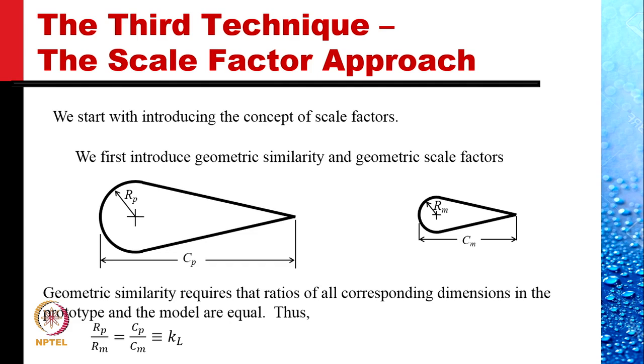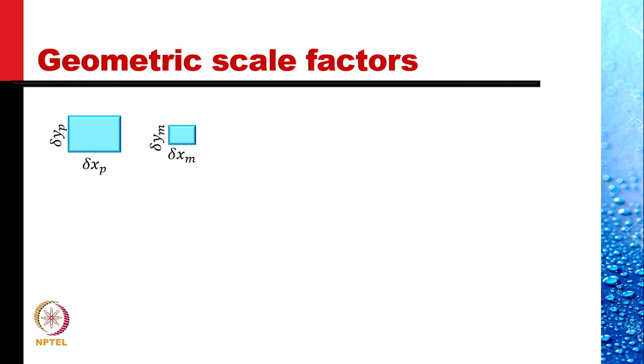So, scale factor is equal to the value of a parameter in the prototype divided by the value in the corresponding model. Let us consider two areas, one in the prototype and the other in the model, the scaled model. Then the area in the prototype is equal to del xp multiplied by del yp, the length in the x direction of the prototype multiplied by length in the y direction.